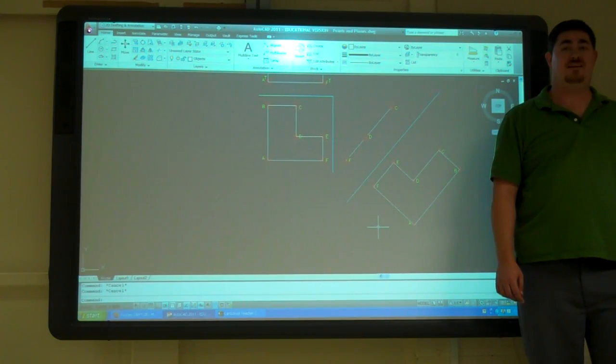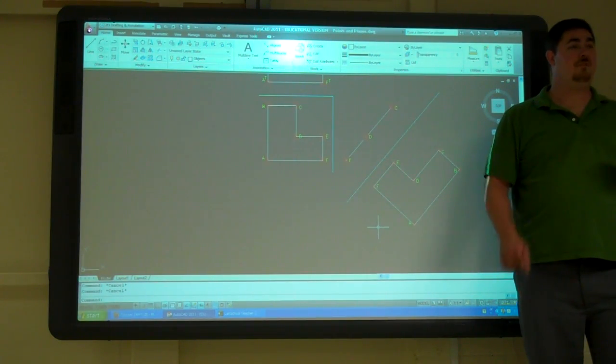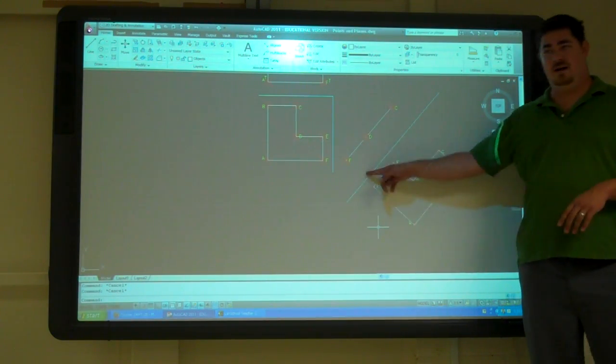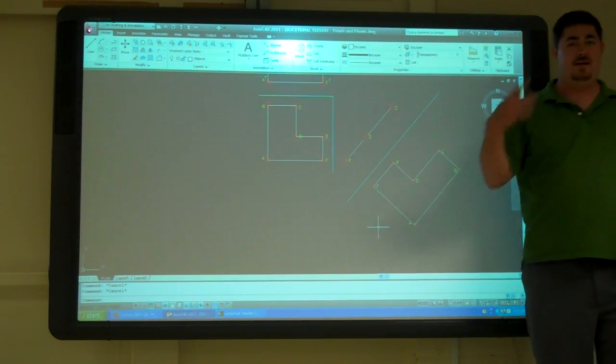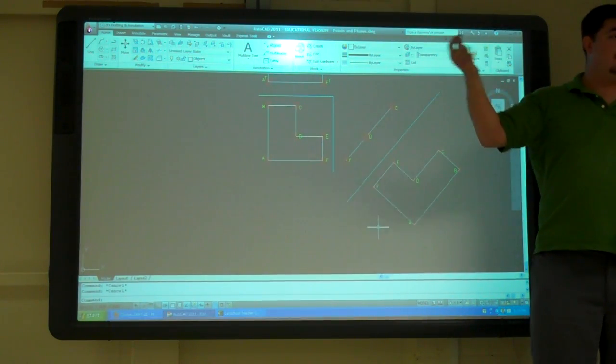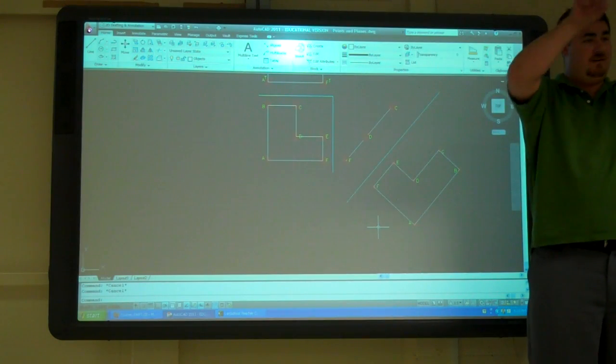Highlight. I think you're on the right track. Did you highlight it and do it? No, solidified into a solid object. Or not a solid object. Yeah, polyline, right? If I make it a polyline, I can make it a continuous line, and then I can just do area object and pick that object to find the area of that shape.